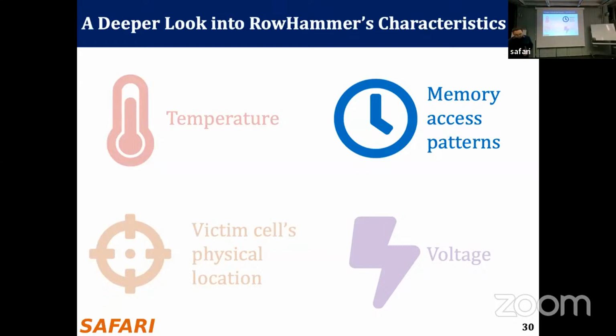I mean, the attacks seem a bit harder with temperature, but defenses maybe easier because the defender has better access to temperature information, and they don't need to conduct a RowHammer attack to defend, right? That's true. Whereas attackers, if they can actually conduct a RowHammer attack, maybe it's not that interesting to deal with temperature-related issues, right? Yeah. So basically, you can sacrifice some capacity. You can choose not to use some of the rows based on their vulnerability level, and then you can avoid read disturbance bit flips. Yeah.